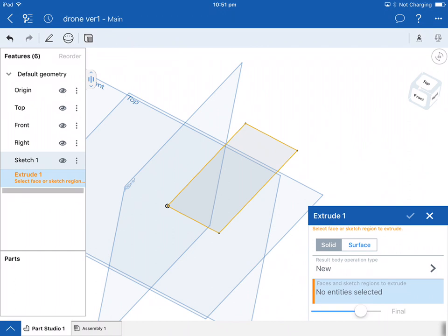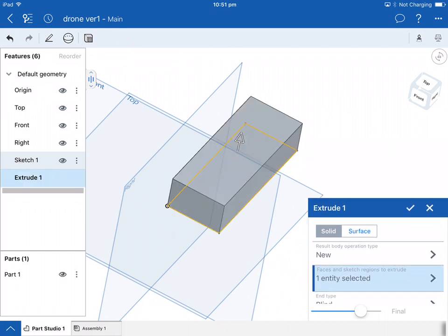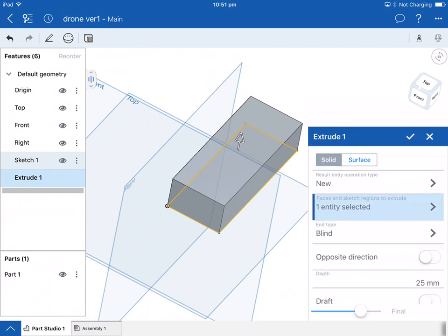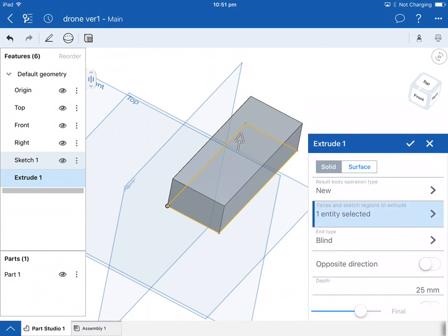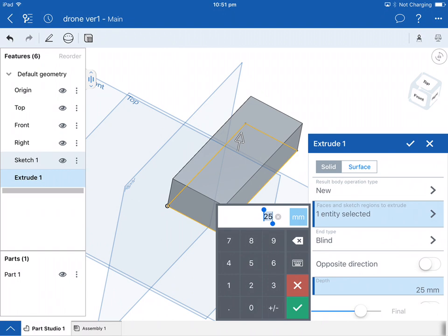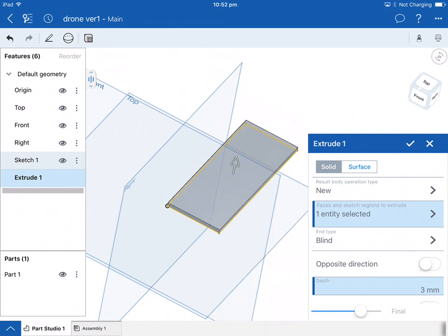and all I've got to do is touch that shape. If I touch in the middle of the rectangle, I can drag this box up and down, and the thickness that I'm after, if I just touch in that 25mm space, the plastic that we use, or the acrylic, or the 3mm ply, it's all around about the 3mm. So 3mm is what we'll work to. You notice that millimetres is showing beside there, and we'll click OK to that.